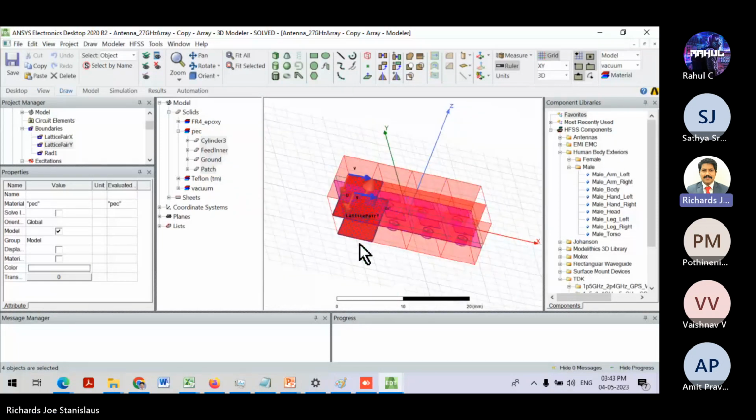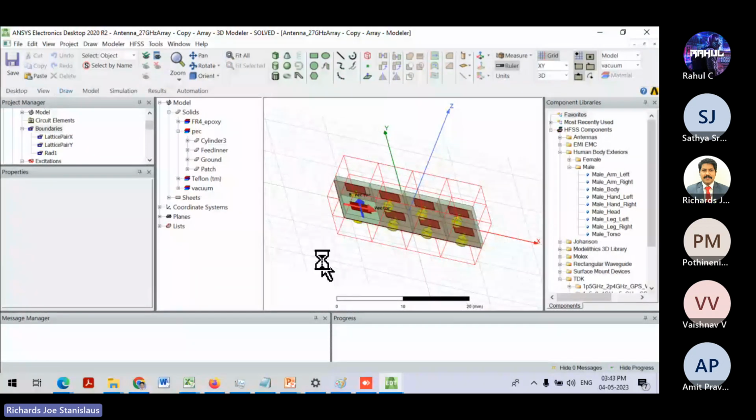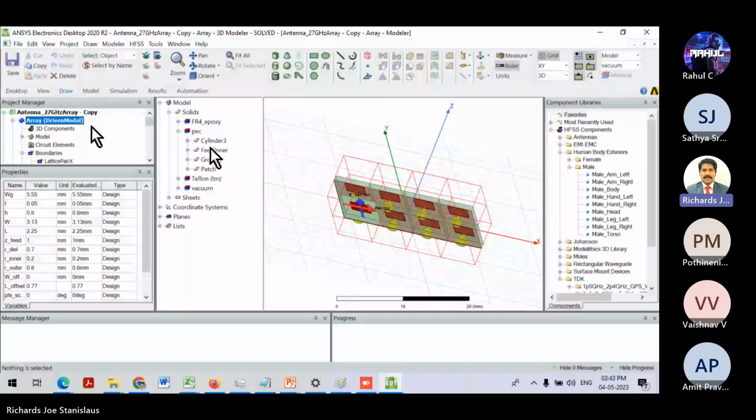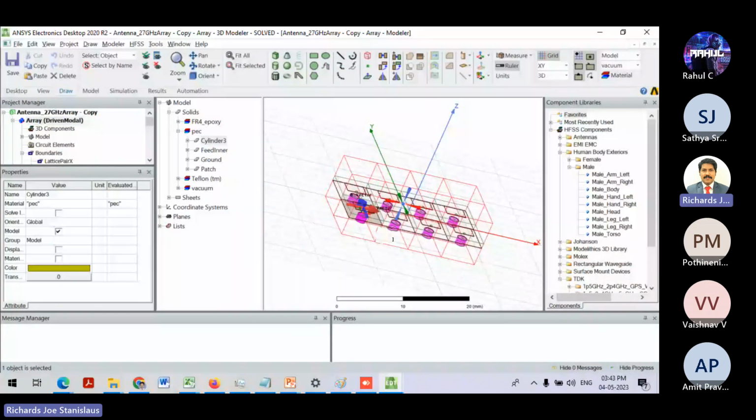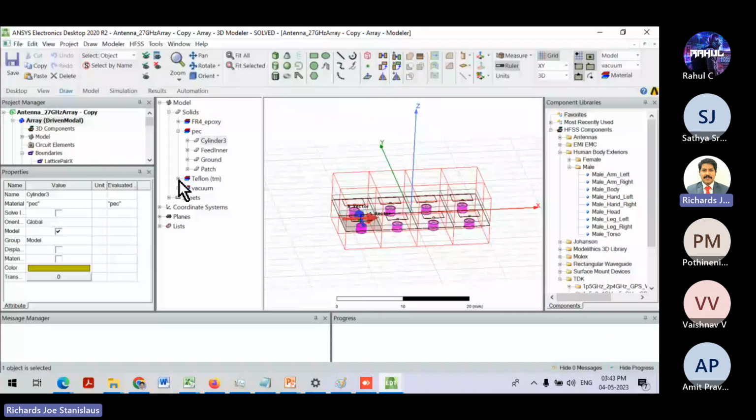RAM can be less, but hard disk space needs to be extremely high, because if you have close to 50 antennas, the simulation result is going to generate 128 or 140 GB of space. It is going to occupy that if you are not using this approach. But with less RAM and more hard disk space, you can perform it. Unlike this domain decomposition method, instead,